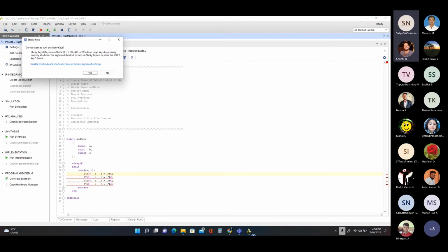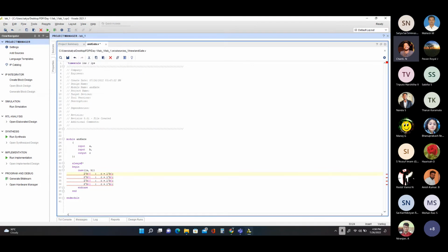So what you do is, after the output C, you declare the type of the net as reg instead of wire. Now that error will go away. There won't be any functional changes at all by defining the type of the output as a reg, but however, you will get the output. This is as per the convention of Verilog.